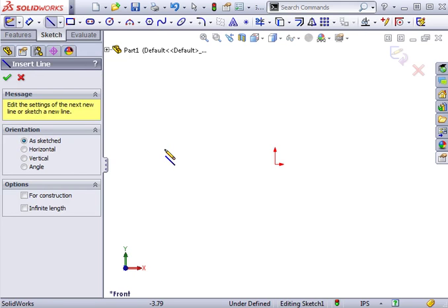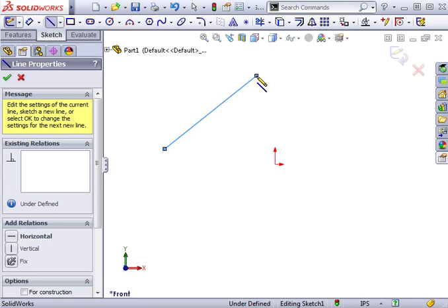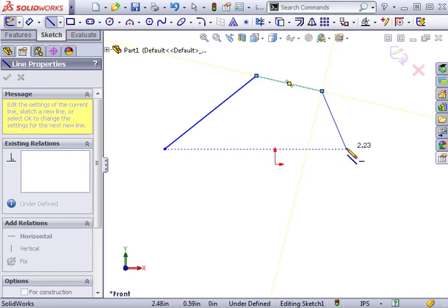To create a line, I click to begin, move my cursor, and click again. After selecting the second time, you can see a point was added, and another line segment has started. This is a convenient way to create a chain of lines. I simply continue to click and more line segments are added.